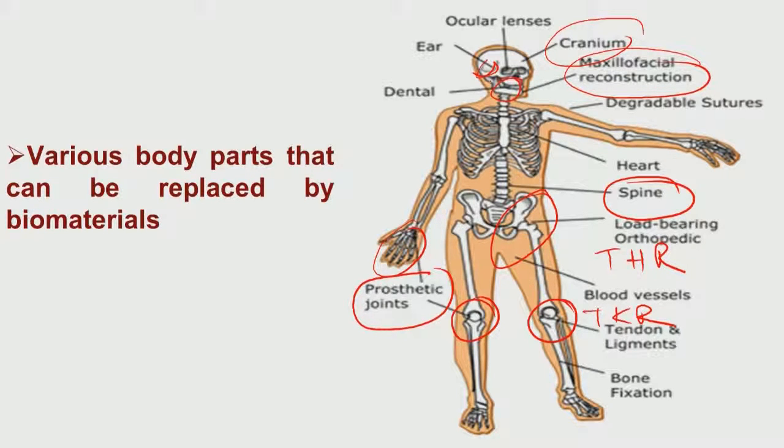And titanium 6% aluminum 4% vanadium, which is used as dental implants, we are currently investigating how one can put a hydroxyapatite coating to provide this kind of implant better osseointegration. At the same time, one can also put, on the abutment part, a diamond-like carbon coating to reduce the frictional properties of this implant material. So, the lesser the friction, the lesser the pain the patients will experience, and it will lead to better health care.